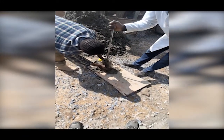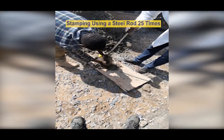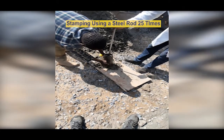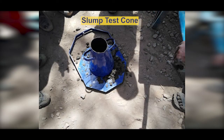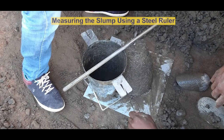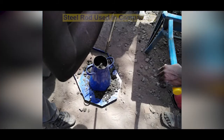And at 21 days, we're looking at above 70% strength. The other test is the slump test. This tests the workability of the concrete, and this is done using the cone method, of course. And for a good slump, we're looking at not anything less than 100 millimeters, and that will be the sure way of testing if your mix designs are successful or not.